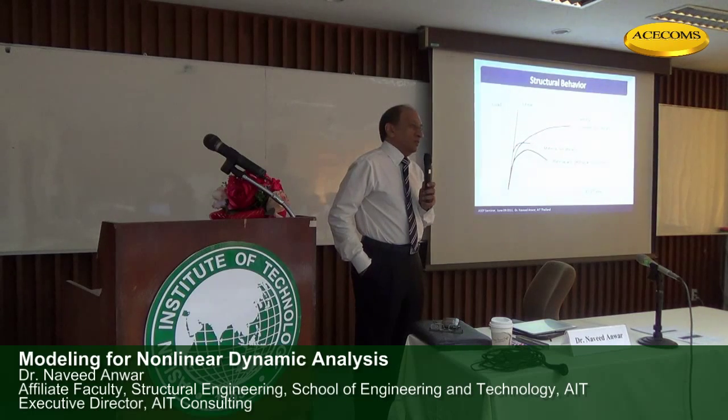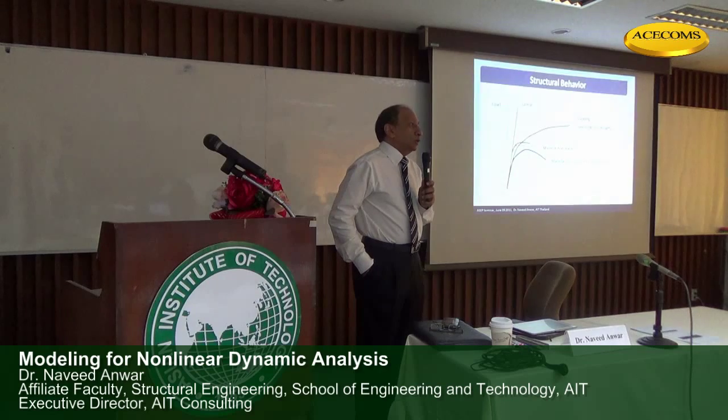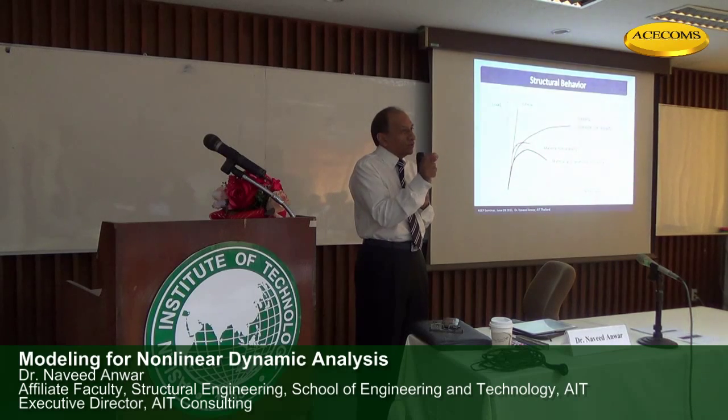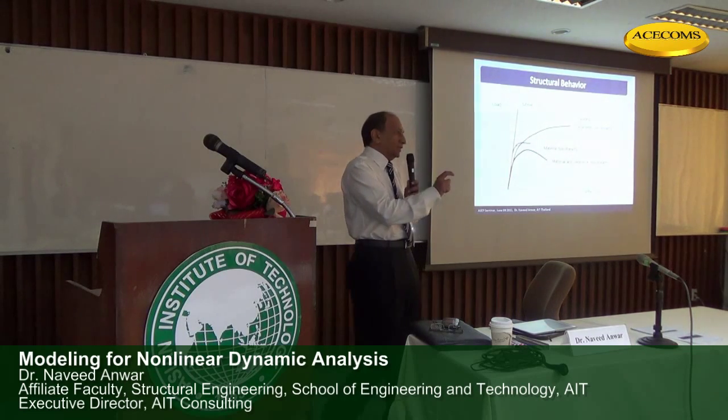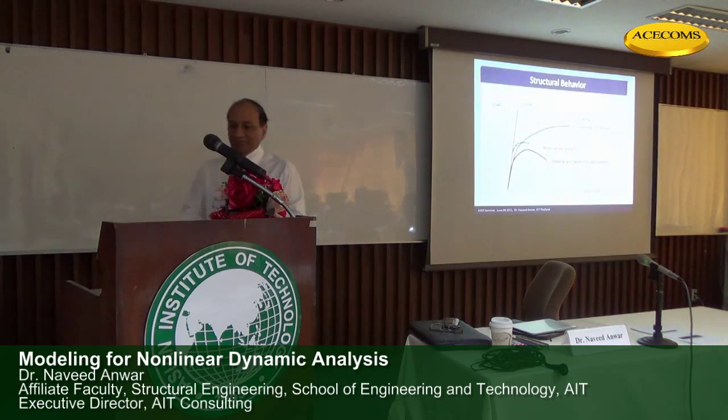The program will not stop you, but you will get nothing, right? You can also try to run a linear analysis on a nonlinear model, which again you will get nothing. So the two have got to go together. The nonlinear model should be correct, and the nonlinear analysis should correspond to that model.